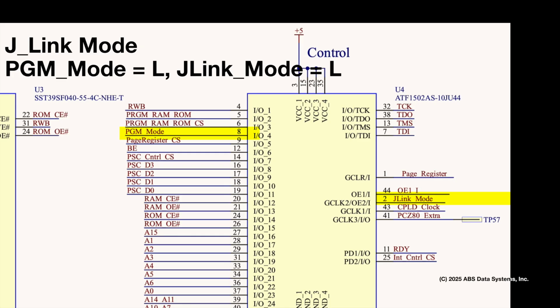My plan is to write the debugger as a desktop application, processing each step as a command to the AVR, rather than having the AVR handle all the debug logic. The desktop has more code space, which will allow me to decode the 6502 mnemonics and display them on the screen. Since we also control whether the CPU is connected to the bus via the BE line, this gives us the ability to read and write RAM locations, which allows us to have full debug capabilities.